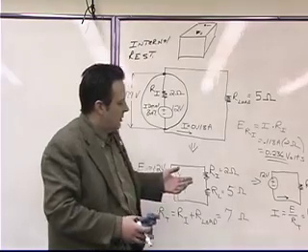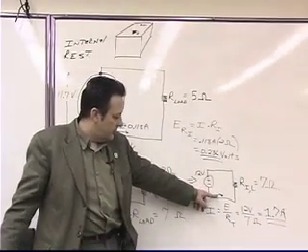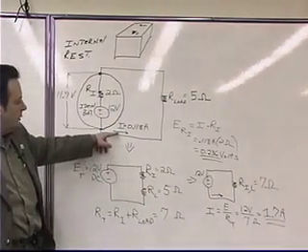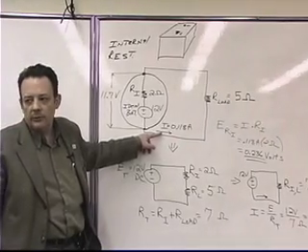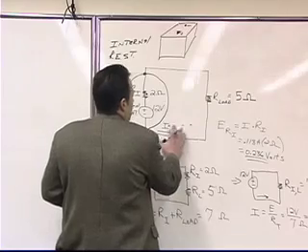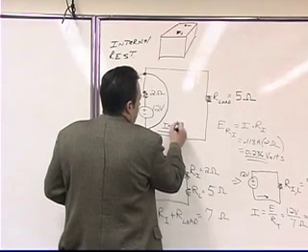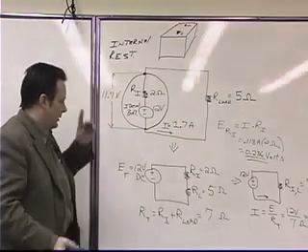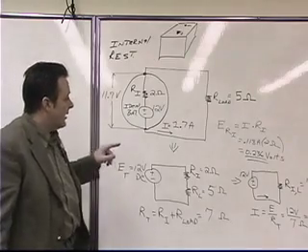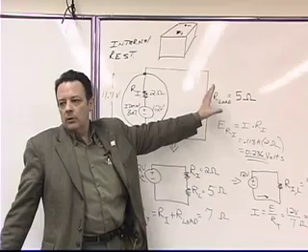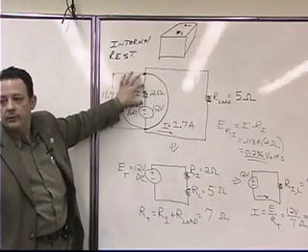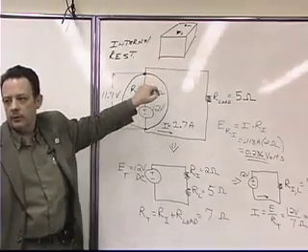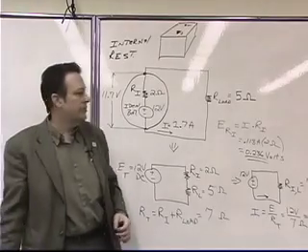Okay, so just like before, if the current flowing in our equivalent circuit is 1.7 amps, then the current that's flowing in our original circuit is going to be the same, right? That's why it's called an equivalent circuit. So we're going to change this current right here to 1.7 amps. And then we're going to take a look at the effect of that increased load on the voltage drop across the internal resistor that's inside the battery, or inside the regulated power supply.